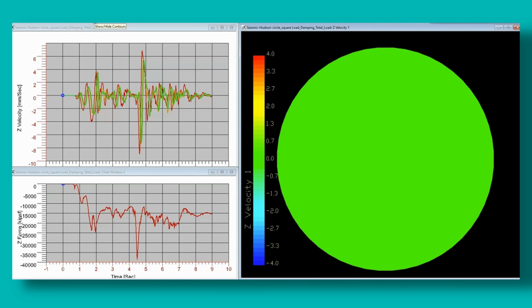This top chart is showing the vibration velocity for 4 elements, while the bottom chart shows that the weight of the structure is 16,000 kips, and 38,000 kips is the maximum impact. Another important observation is that when the load becomes constant towards the end of the simulation, the vertical velocity drops to nearly 0. This is exactly what we expect physically, since a constant force does not produce additional acceleration once equilibrium is reached. The second conclusion is that the truncation method, where the user only considers the duration of the peak load instead of the entire loading history, was an acceptable approximation for this case.